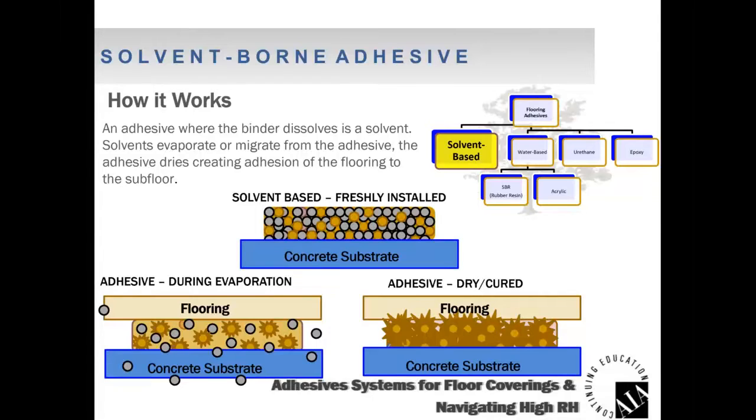All right, so back to solvent-borne. You see that I don't have that as solvent-based. While there still may be some solvent-borne adhesives out there, such as a contact cement, basically the solvent, no matter what that solvent is, is the carrier. It could be mineral spirits, acetone, naphtha, hexane.